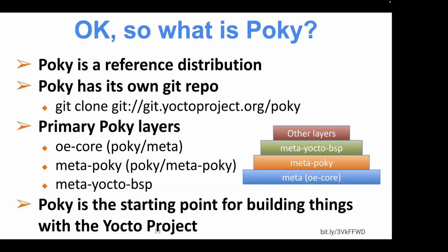You'll find that in a lot of presentations surrounding the Yocto Project and OpenEmbedded, it kind of looks like there's a fixed number of layers. There are not. There's as many layers or as few as you want. The more you stratify the decisions and metadata that you use, the more you can reuse them to a large degree. The tendency, of course, is to start adding code at a layer near the top of the stack. And then the more generic, the more useful that metadata becomes the further down in that stack.